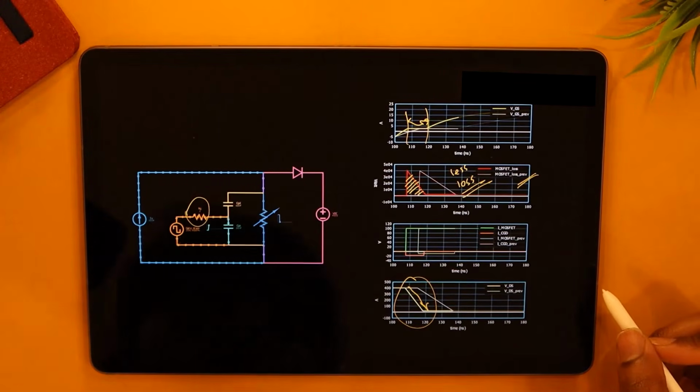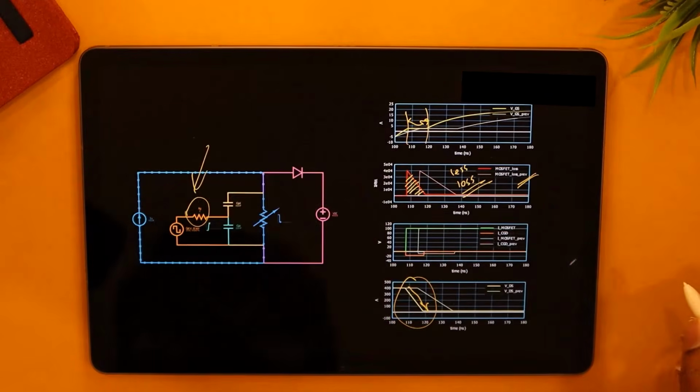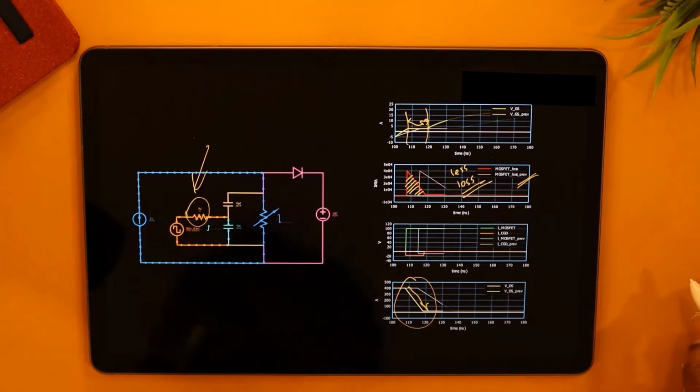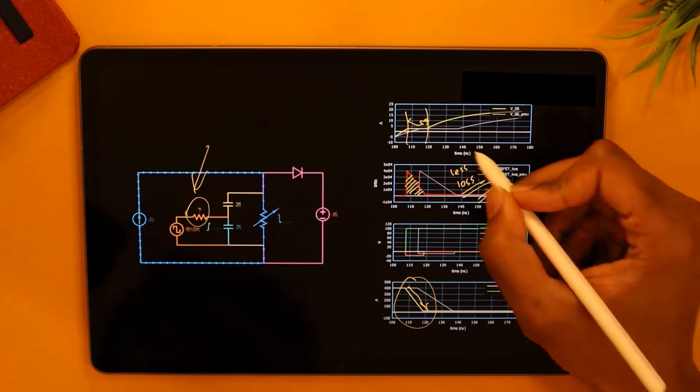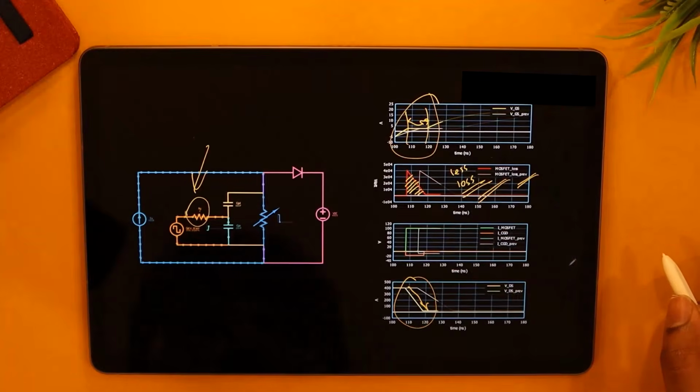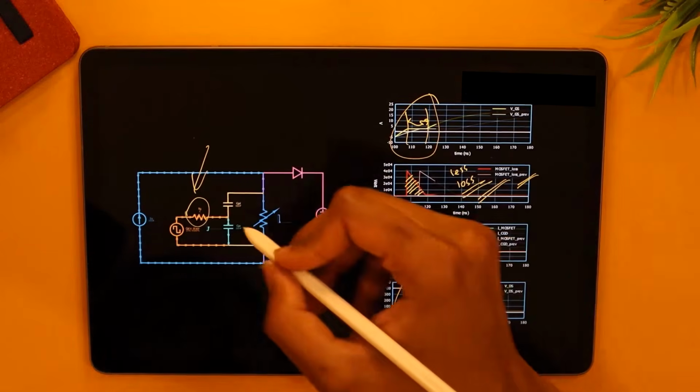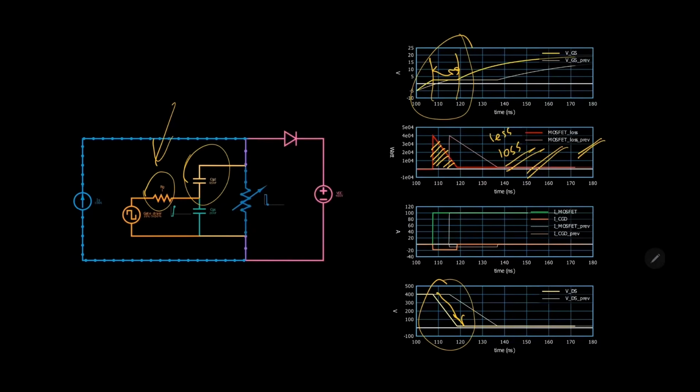So this is how important that gate resistor is. It's another control handle you have, to tell how fast you want to turn on your MOSFET. The faster you do, the lesser is the loss, the lesser is the plateau. That's how it works. Now, what else do you think can affect the plateau? What about CGD itself? If I got a really bad MOSFET from the market that has a really bad value of CGD, here I am using 0.5 nanofarad. What if I have a MOSFET which has a CGD of 1 nanofarad, twice the value? What do you think will happen?